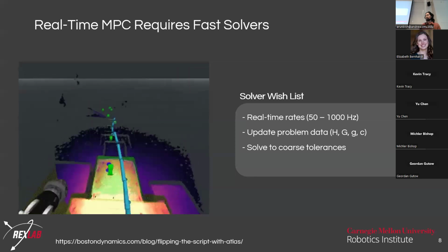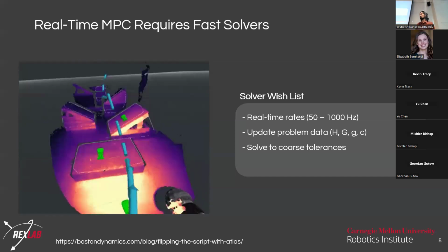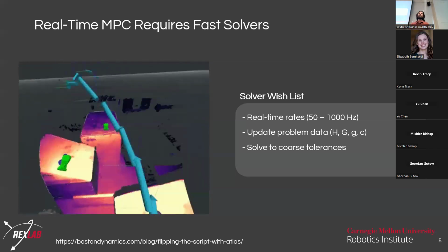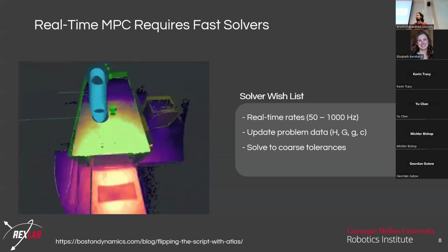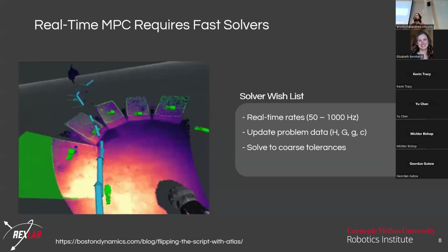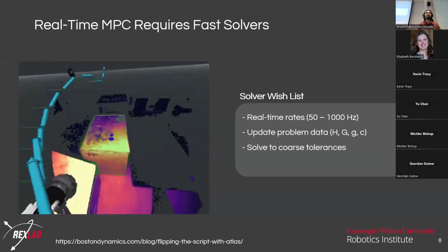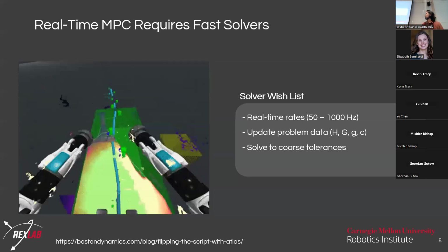And the way to think about this and why we don't care about super fine grain accuracy is first, the longer you spend, the more latency you're adding, the less responsive your controller is going to be. And also there's always going to be errors in the model and stuff like that. So there's a point of diminishing returns where you want to get to something really fast, apply that, get the new state, and just go as quickly as you can.